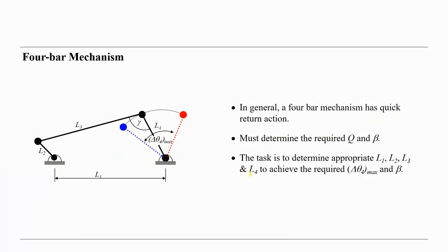And we said quick return is sometimes important because the forward motion of a moving part is mainly used for a process, and the process maybe has a special speed, so we cannot drive too fast. Therefore, the speed for the advance stroke or advance motion has to be controlled and adjusted according to the needs of the process.